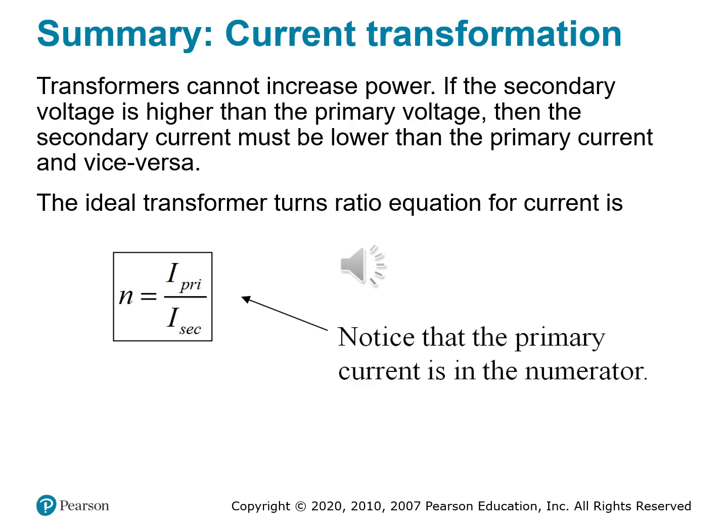Why does this matter? If you're using a step-up transformer to increase voltage, the device on the secondary side will draw less current. If you're stepping voltage down, the load must receive more current to maintain the same power level. This is especially critical in power distribution systems, where stepping voltage up minimizes current and reduces the I squared R losses. In other words, I squared R, those are losses that we experience in circuits.